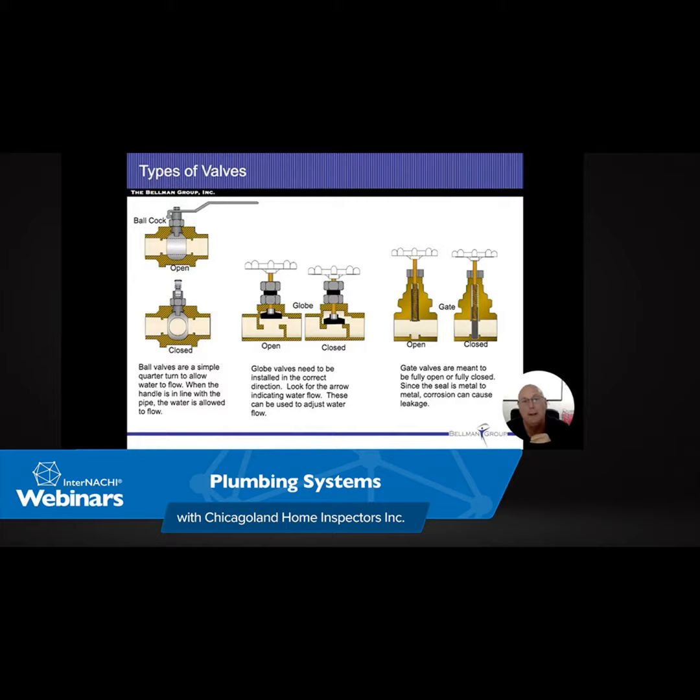All right. Sometimes we can use the soil stack as our vent, so we don't have to have an auxiliary. What we don't want to have happen is where our trap comes and it goes back up, and then on the top of that U, I don't want that to continue straight up to be my vent. It's got to make a turn, and as it makes a turn, then we want to go ahead and put the vent. Typically 5 feet is a decent number that we're going to run into for most sinks, all right?